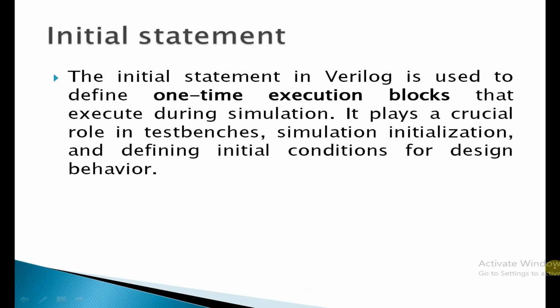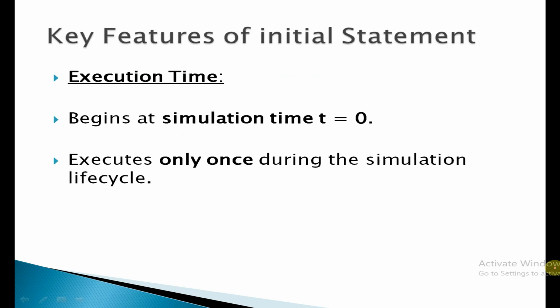Regarding the initial statement, we saw in the previous session that the initial statement in Verilog is used to define one-time execution. The initial statement will start at time t equal to 0, and it will execute only once during the simulation time period. The key features of the initial block are that it starts at time t equal to 0 and executes only once during the simulation life cycle.